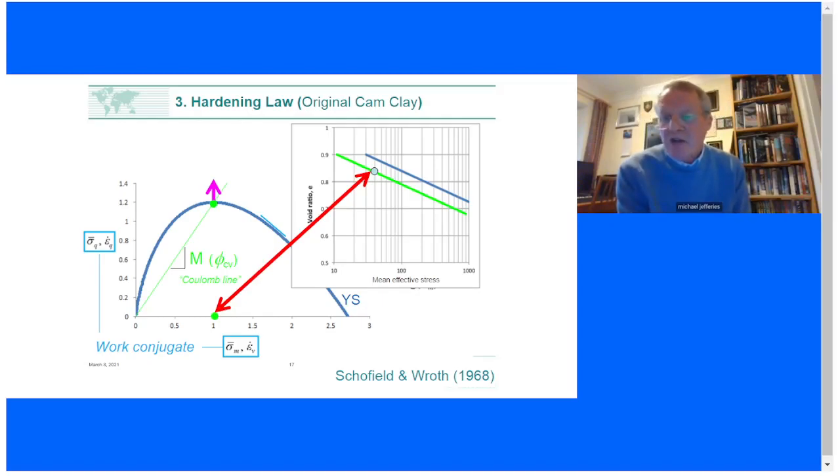That tells me the stress in the critical state, or the mean effective stress in the critical state, is about 40 kPa on this cartoon. That means my strength, or my axis on the horizontal axis there, my green dot is at 40 kPa. So I can now scale my soil strength behavior from its void ratio. And that is the elegance and power of critical state soil mechanics.